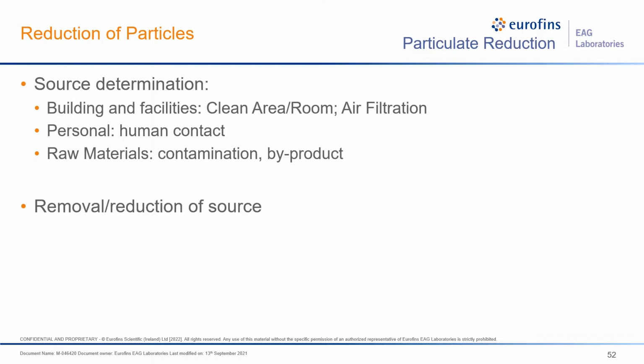And these you may have ways to remove them, like maybe rinse the part before using or transferring into your clean room. And some of them we see are byproducts. Your raw materials are fine as is, but when two things meet each other, they may not be compatible. When they're incompatible, they could be reaction products as well. Once we limit the source, what they are, our next part is removal and reduction of the source. My team can help you figure out either we do a rinse or what's the necessary step to avoid further contamination of these particulates.